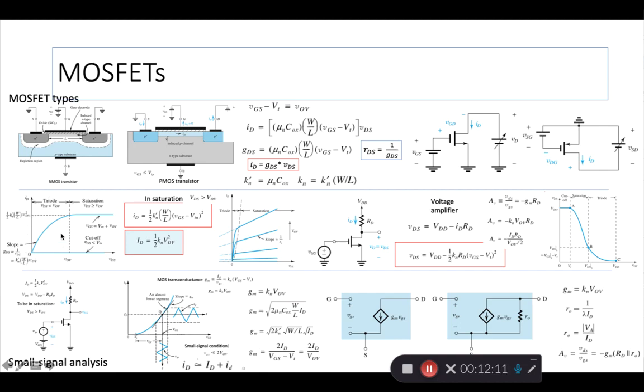Okay, but this slope is the GDS that was introduced here, and this is the value for GDS. Actually, GDS has many formulas, but one formula is this Kn prime, W by L, and overdrive voltage, which is what is shown here. And then the current here, the saturation current, or the current when the transistor is saturated, stays pretty fixed, except if you take into account something called channel length modulation, which I've tried not to bring in here because it just confuses everything.